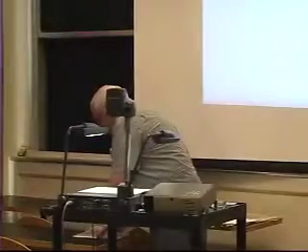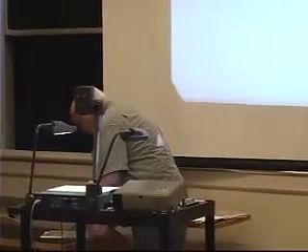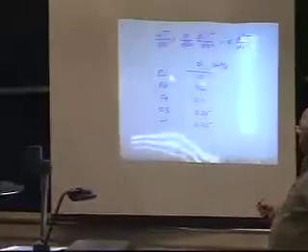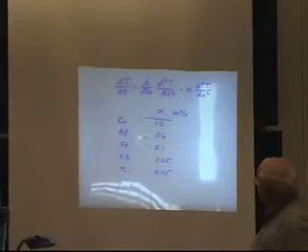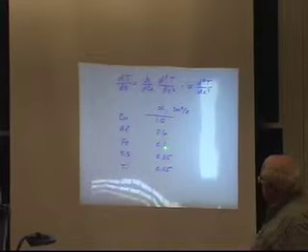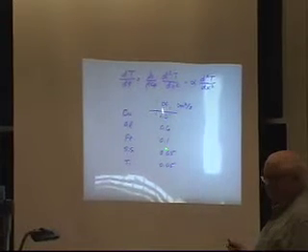Okay. So what is the alpha number? Where does that come from? Alpha is thermal diffusivity. Right. Okay. And so I actually gave you a handout of a little thing I wrote in the welding handbook that gives different values of alpha, just to give you an idea. So we have copper, alpha is 1. Actually gold is the highest, about 1.2 or 1.3. Aluminum is 0.6, iron is 0.1, 10 times less than copper.